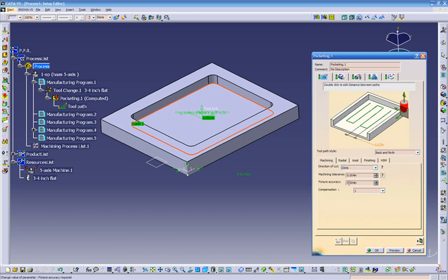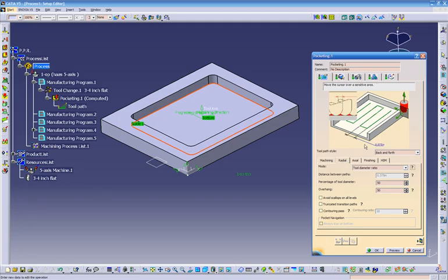Over here is the tolerance. You can see over there. Radial. It's asking us over here for the tool diameter. So you just put over here kind of like a step over. Right now it's 50%, so the step over ratio is 50%. Or we can put it to distance. Right now we put step over 375. Step over from here to here, we get 375. Or we can put the step over ratio or maximum distance.